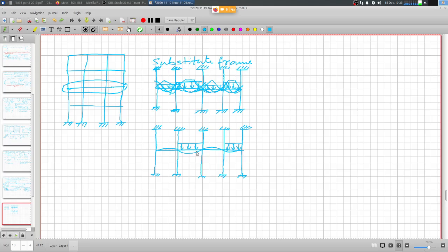Right, so I'll read out the loading pattern considerations. The arrangement of imposed loads, you will find design dead load on all spans with full design imposed loads on two adjacent spans, and design dead load on all spans and with full design imposed load on alternate spans.